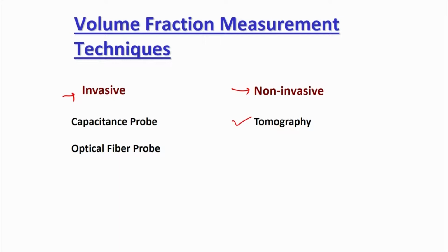For invasive techniques, there are again several available. Even using the pitot tube or the pressure probe you can measure, but I will keep the pressure probe separate. Basically, two techniques are majorly used to measure the volume fraction under the invasive umbrella: one is the capacitance probe and the other is the optical fiber probe.